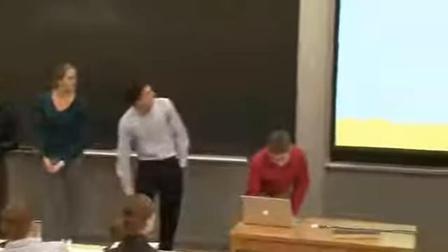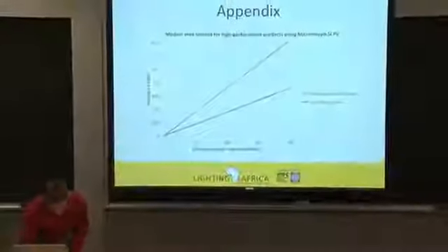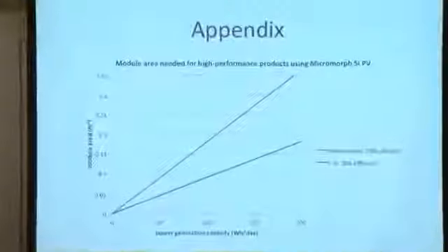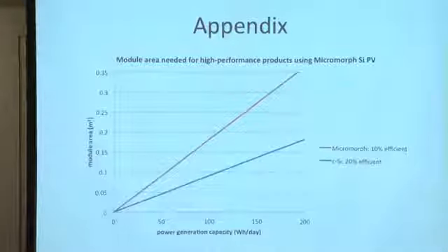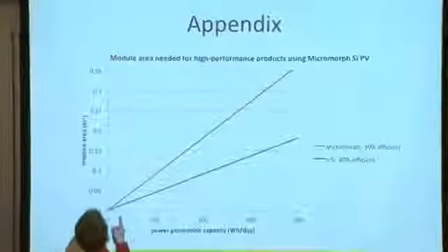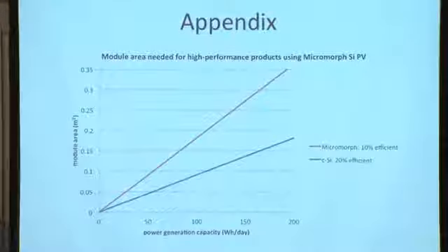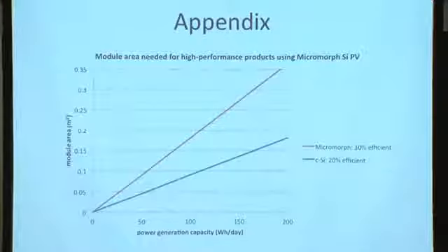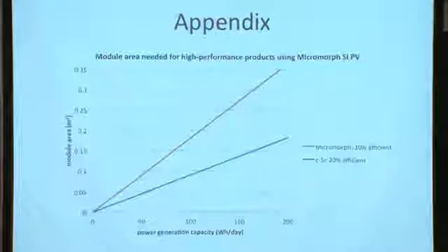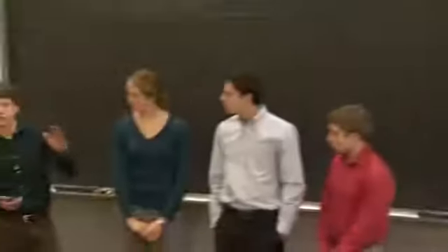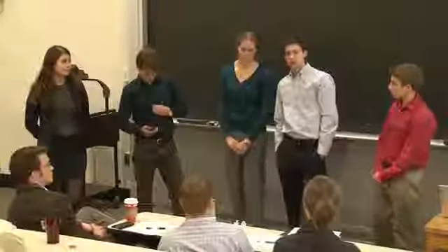Yeah, so charging a cell phone. I mean, if you want lighting and cell phone, how much does that add to the cost? Yeah. Is there a larger market for that? So there could be a very large market for that because it doesn't actually take that much energy. It takes about 4 watt-hours to charge a cell phone. So for a very basic device that maybe produces 9 watt-hours a day, you could get 5 hours of light, for instance, depending on the efficiency of your LED, and then also charge a cell phone. So it's not a great threshold to overcome to be able to charge other things, especially cell phones. And the non-PV aspect of the cell phone charging is also very cheap.